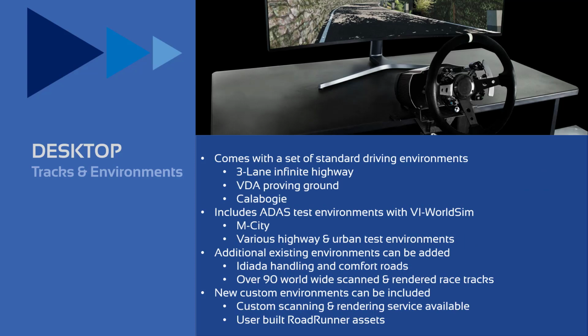For simulation tracks and environments, a desktop simulator comes with a fairly large set of included and available solutions. We provide a 3-lane infinite highway for acceleration and deceleration and lane change dynamic testing. We include a VDA proving ground that comes with various size circles and a broad, wide area to drive on. It also supports adding cones for slalom and lane change tests.